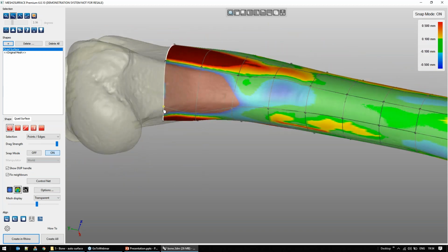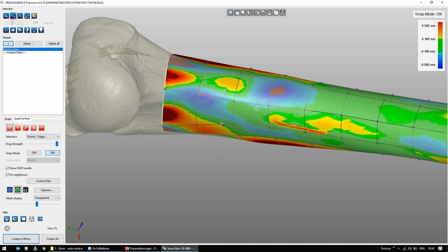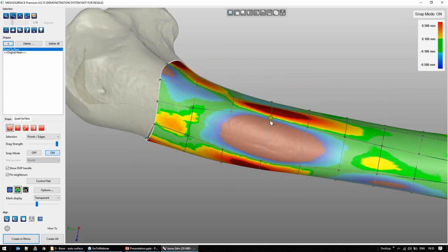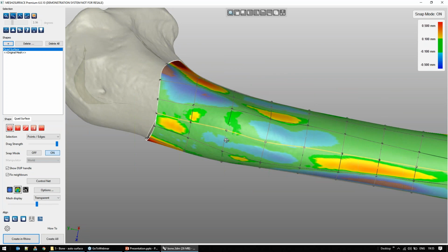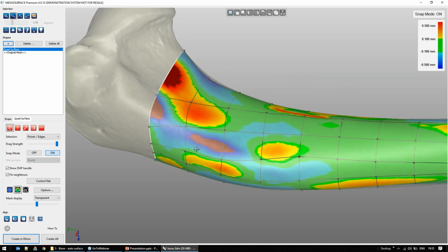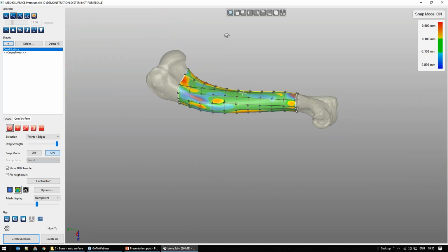Again, this is just a normal surface where you can create a deviation analyzer. You can improve your shape by dragging and dropping on the mesh. Or if you want to improve the quality, you just select an edge and then press the S key, and it automatically splits the whole chain of faces, and this is how you improve.